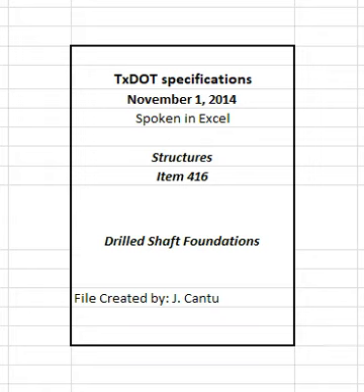Install surface casing to a minimum of 10 feet below existing ground before introducing slurry. Do not use casing other than surface casing. Do not use surface casing longer than 20 feet without approval. Do not extract the surface casing until after placing the concrete.